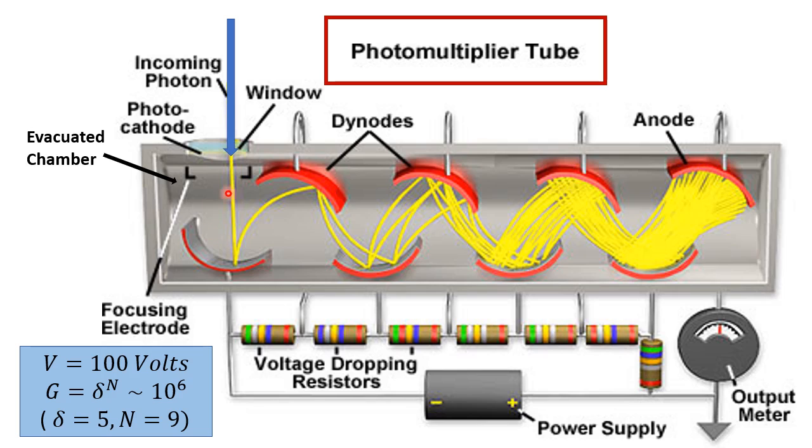releases an electron. Now these electrons are, as I said, focused and accelerated between this electrode here and this electrode here. So the typical voltage between this is about hundreds of volts, and that leads to acceleration of this electron along this path. Again, these electrons hit here and they release many more electrons. And typically, for example, if the multiplication factor is, let's say, for every impinging electron you release 5 of them, you see that 5 electrons are now again refocused onto the next terminal.